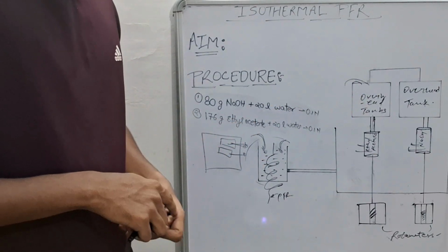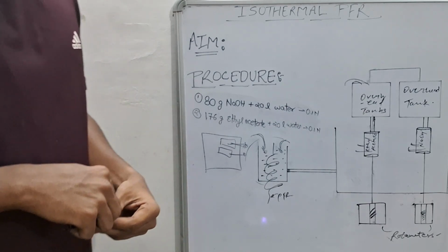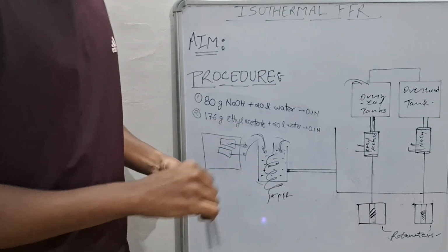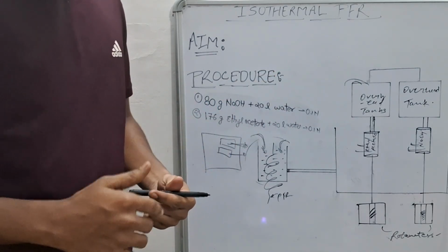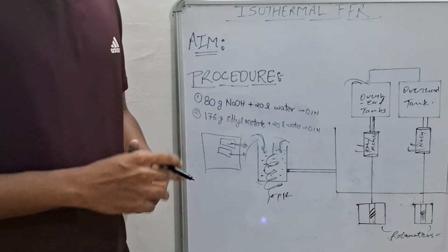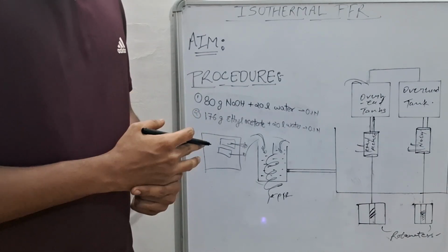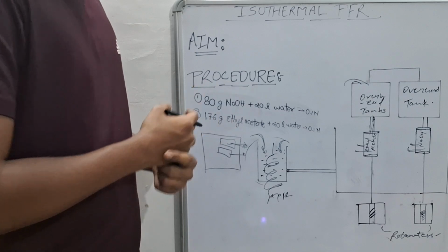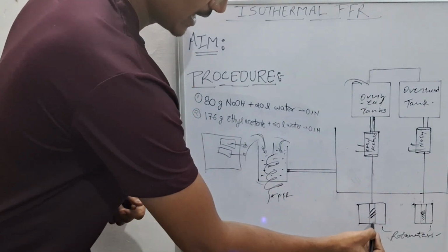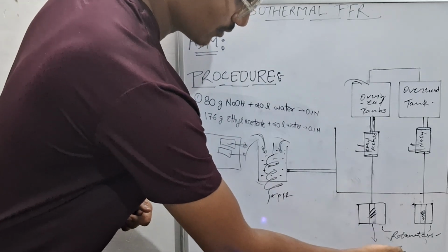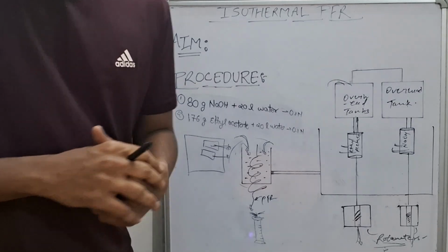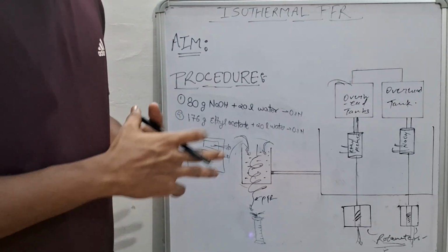After that, rotameters come into the picture. Using rotameters, we can adjust the flow rates of both the streams, so that they are equal. For example, if we maintain a flow rate of 10 lph, we achieve the equimolar rate. In this way, we use both these rotameters, and both the rotameter flow rates should be equal to achieve equimolar concentration. So after setting up equimolar flow rates, now let's proceed further.